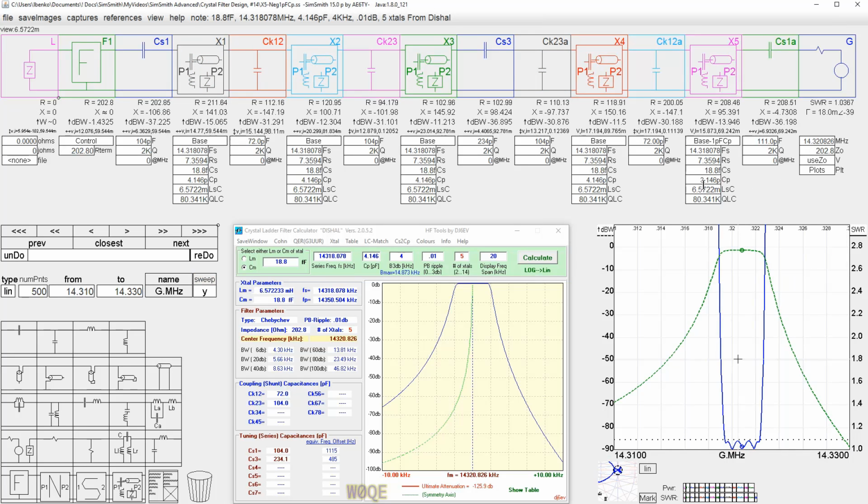So, it used to be 4.146, it's now 3.146. We can see that if we change this capacitor just a little bit and change none of the other capacitors, we can get the SWR down again to the same level we had before. That's very nice. That means that we can compensate for a small amount of change in parallel capacitance. It turns out we can't compensate for a large value of change, but the parallel capacitance is never that big of a change anyways.